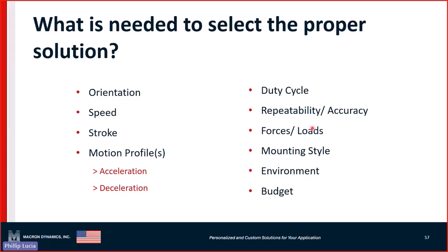So it's all the standard questions you would ask. I would throw in the extra thing you would need is what's the moment loading on the device, especially a linear actuator. The moment loading is important to make sure your bearing structure can handle it. So I guess that kind of closes up my part of it. I'll leave you with this. As a sales organization, one thing to think about is the mechanics on a project are designed first.